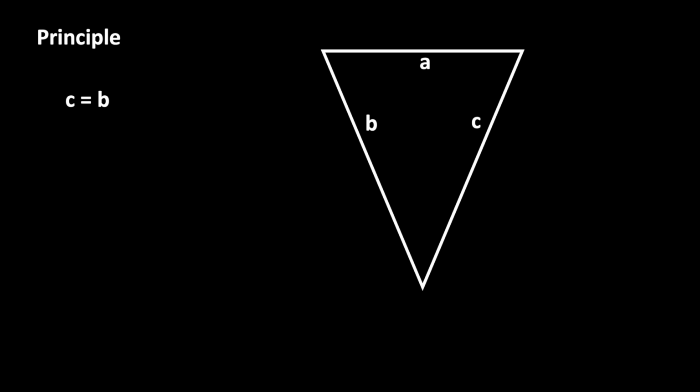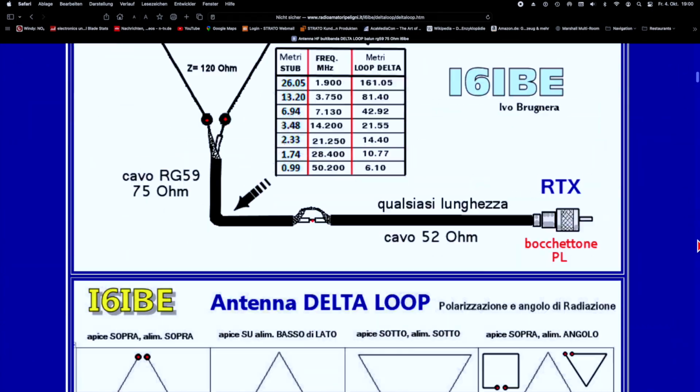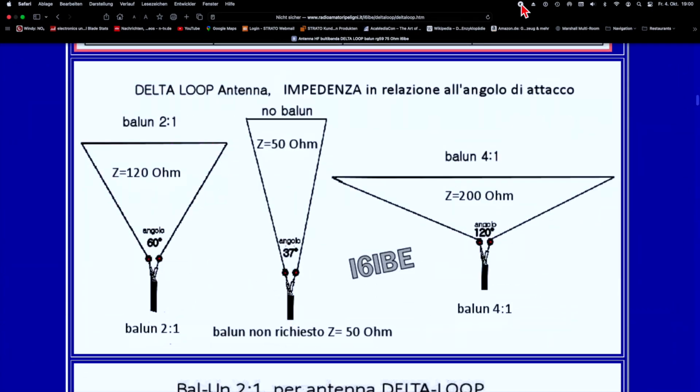As a loop antenna's impedance is usually hundreds of ohms, you need a suitable matching network. Interestingly, you can dimension the delta loop to exactly 50 ohms impedance. Its setup is pretty simple and therefore suitable for use on the go. I came across this by chance. Clever people figured it out long before me.